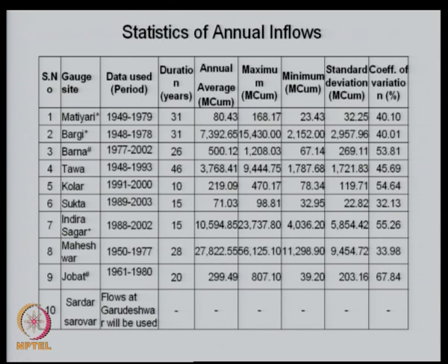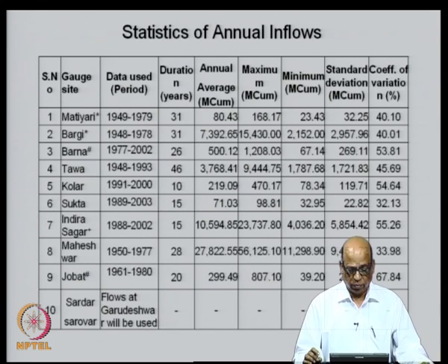So, the first level exercise, as I have been repeatedly telling, is just to look at the statistics, compute all the overall statistics of the flows. Typically, when we are dealing with hydrologic designs, we will be dealing mostly with the flows, and then get a feel for what you can expect from that particular system.